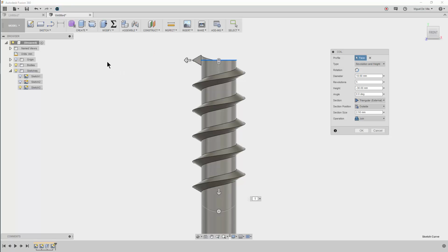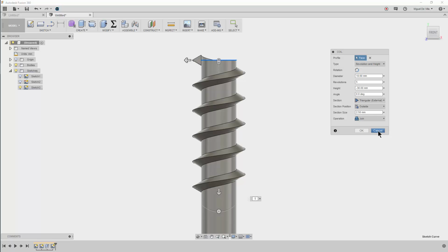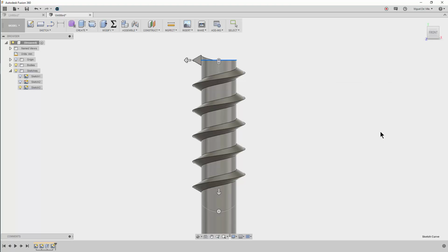Well, shortly we will be using the project 3D geometry function of the sketch environment along with a sweep from the create environment. We could combine those two to generate a helical extrusion based off of the 3D geometry of this coil and attach it to our own custom profile and then sweep all that to make our own custom threaded feature. So let's begin.